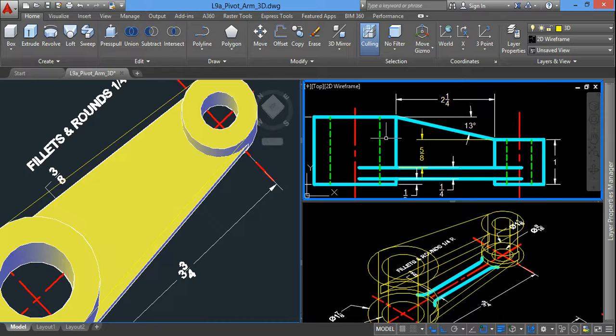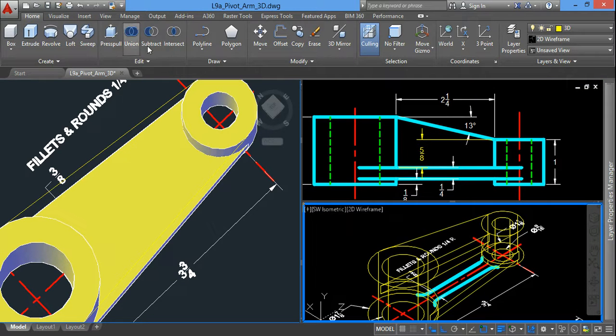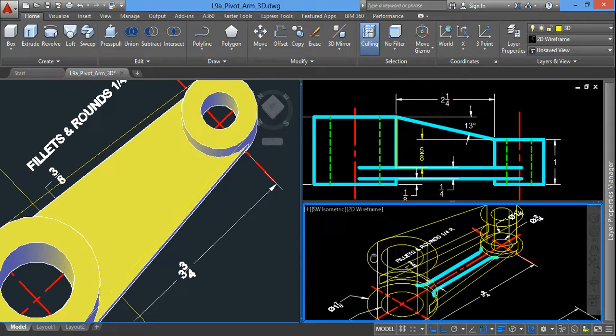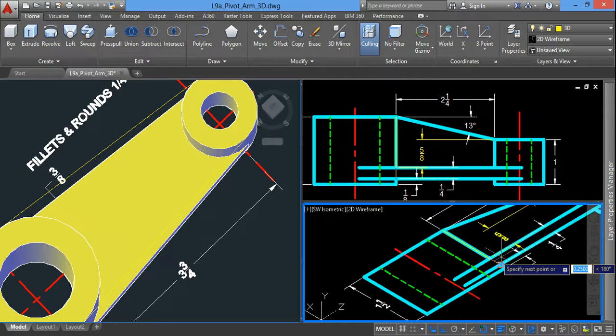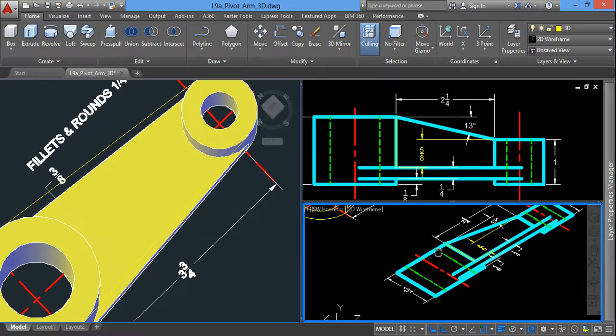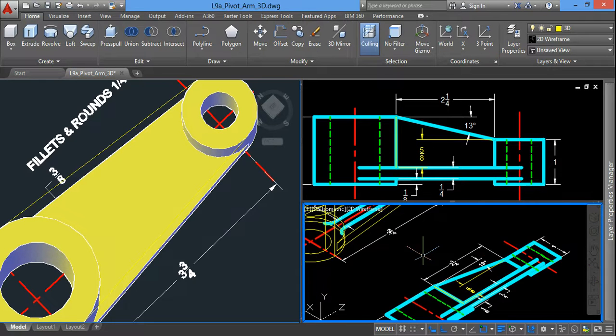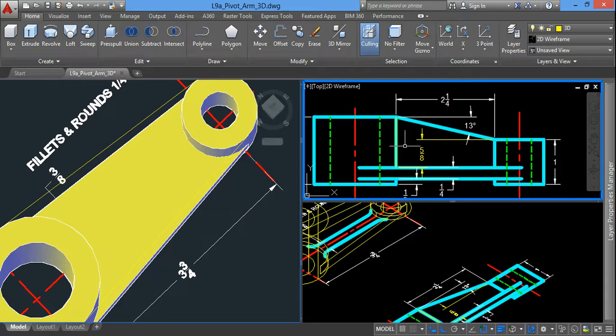If I were to make a trapezoid here, but I start here and click the Polyline command and then click over here, it may not allow you to draw the polygonal shape. As you see, I'm not able to. I can't grab this point here. I can't grab this point here. I can only pick these 2 points here because this vertical y-axis is related to the orientation of this axis. So let's take a look at what I drew. I just drew lines up and down on this feature. So that doesn't work. Okay? So that line right there is irrelevant to me. I need to click in the view first and then draw.